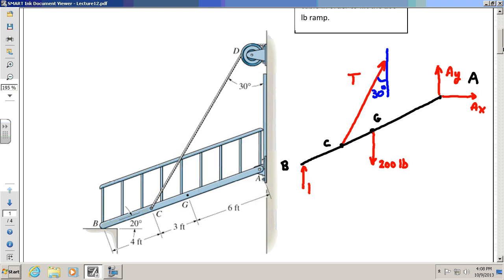Clearly in the picture it's touching the ground. So I'm thinking there's going to be a ground force on the ramp, because you always want to look where your ramp is touching. It's touching at A and it's touching ground at B, right? It's touching ground both at A and B, plus it has a rope. So those are 3 points you have to put forces on.